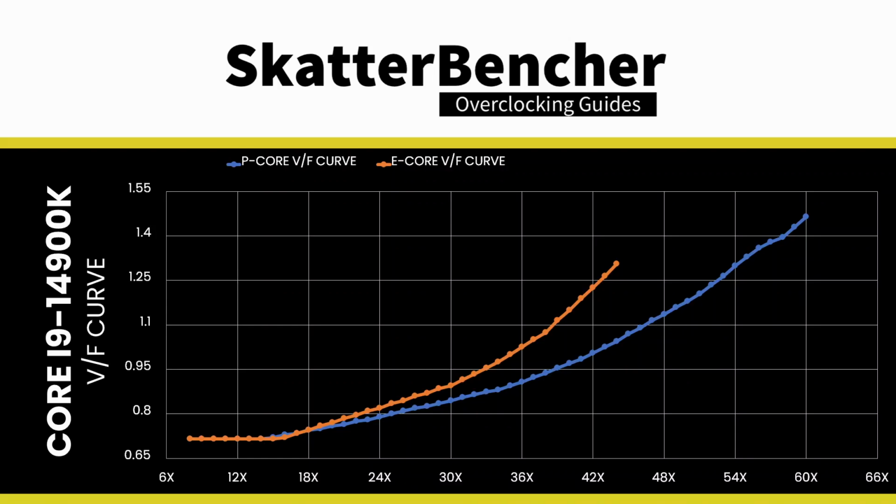For educational purposes, I also extracted the VF curve for this CPU's P-core and E-core. The VF curve is a factory-fused voltage frequency curve per core that describes the relationship between a certain ratio and the voltage required to run that ratio stably. In my case, the CPU has a P-core VF curve that goes from 8x at 0.715 volt to 60x at 1.465 volt. The E-core VF curve goes from 8x at 0.715 volt to 44x at 1.265 volt.